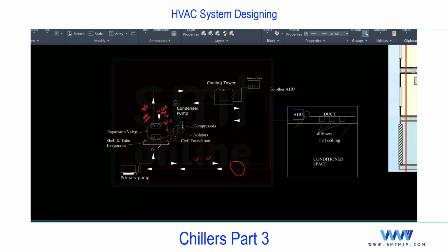So you see that the difference is nearly 10 degrees. Even here in the supply and return, suppose 54 and 44, the delta T is going to be 10. And remember, this delta T will be used at the time of pipe sizing. Based on this, for this side we have the conversion 1 TR equal to 2.4 GPM. This is just a preview, just remember this. And for this side, we have 1 TR equal to 3 GPM. And why this difference in the flow rate? I'll just give you the idea. The detail we'll discuss in part 5.